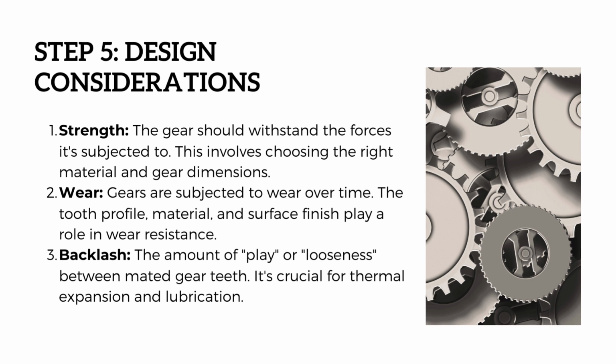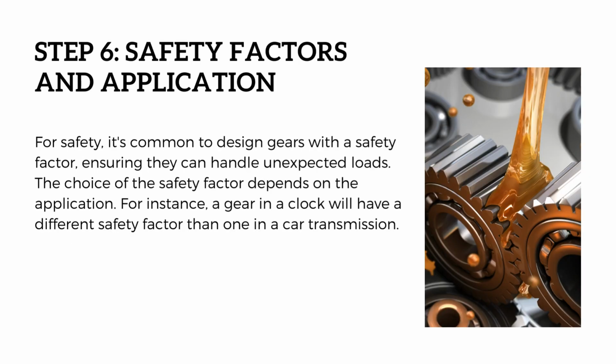Additionally, backlash, defined as the play or looseness between paired gear teeth, is critical to account for, especially concerning thermal expansion and effective lubrication. In Step 6, the emphasis is on safety factors and their application in gear design. Gears typically incorporate a safety factor to ensure resilience against unforeseen loads, with the specific factor contingent on the gear's application. For example, the safety factor for a clock gear will differ significantly from that of a car transmission gear.